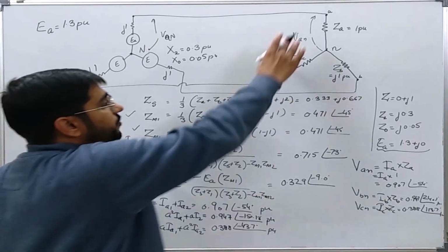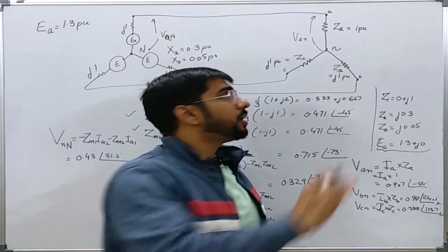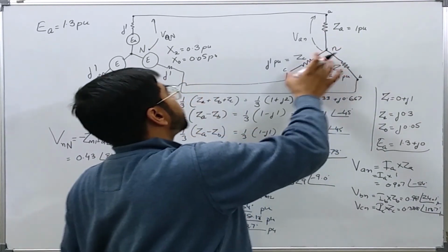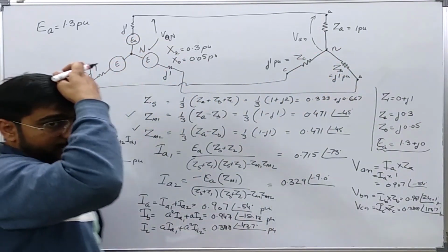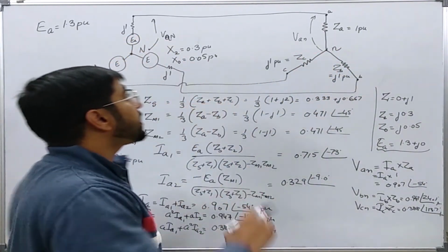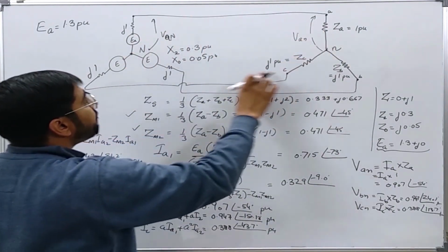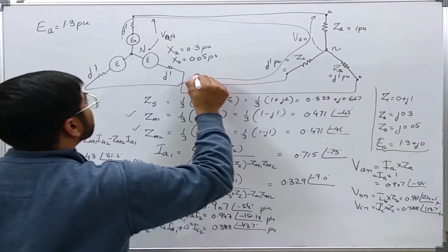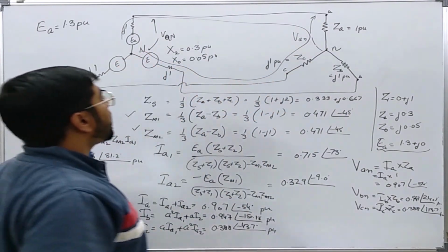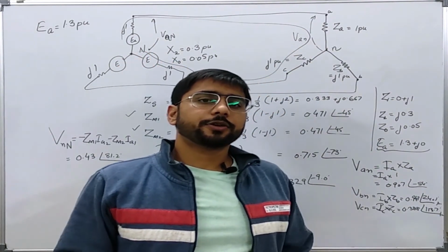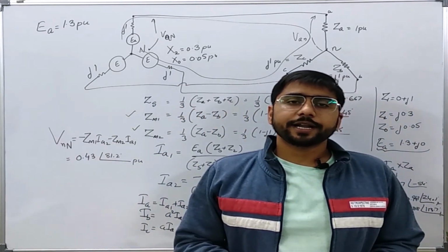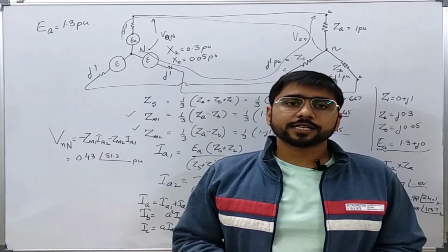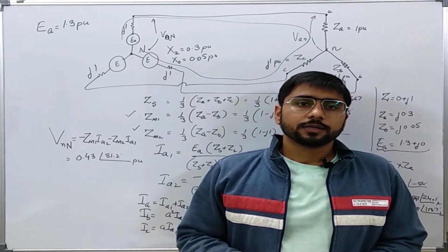Now all of these voltages are on a base of line-to-neutral voltage. So in this way, instead of using KVL and KCL in various loops or meshes, I have utilized the theory of symmetrical components in solving such a numerical example of circuit theory.